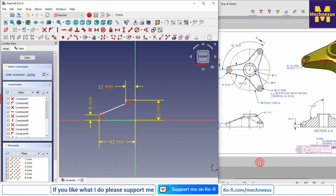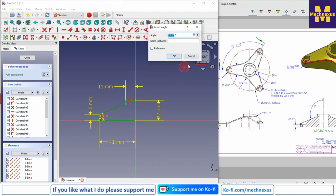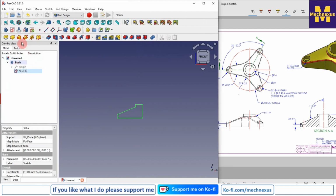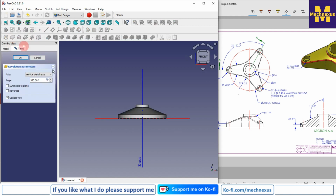Here the angle dimension is given as 112, so this will be 68. So I will select this and this and give the angular dimension, this to this, angular dimension 68. Say OK.